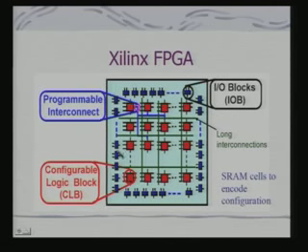These are your I/O blocks. Depending on your interface to the external world, these I/O blocks can be set. So, in fact, what is your programmable part of the logic? You can synthesize what these logic blocks can do, how these logic blocks have to be connected, and also what kind of inputs should come into each logic block.